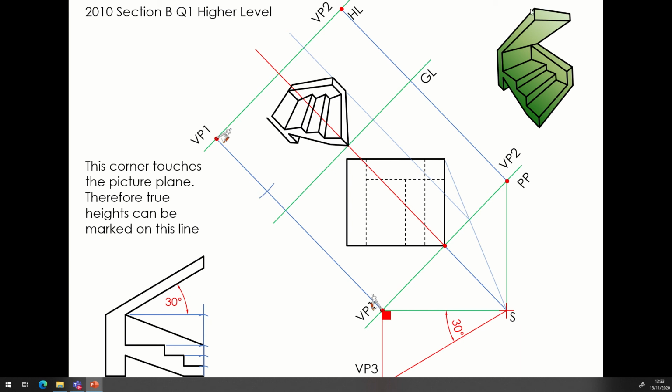And then to draw in our slope lines now, all we need to do is say, well, we have our front point here, our back point here, that's this point here and this point here. All we're going to do is simply take vanishing point 3 and project them up through that. So that represents our leading edges here moving up. All we need to know now is the position at the front, which we have already, our corner A. So there is our corner A, giving us the full side of our piece here like that.